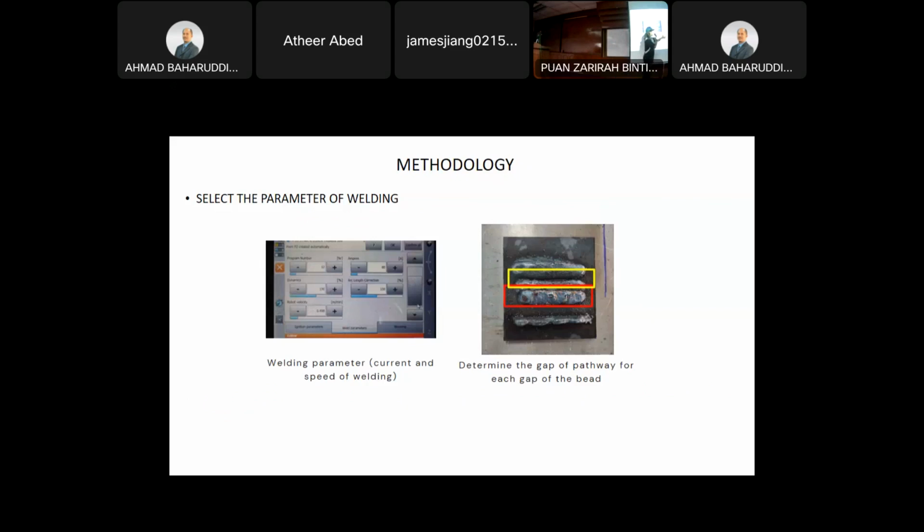And this picture shows the gap between the different lines of deposition, the length of the deposition gap. So the first one is between this and this, actually 0.5 centimeter. I have done it with the same speed 0.598, and this one is 0.3. As we can see, there is a little gap in the yellow part, and this one is attached to each other.